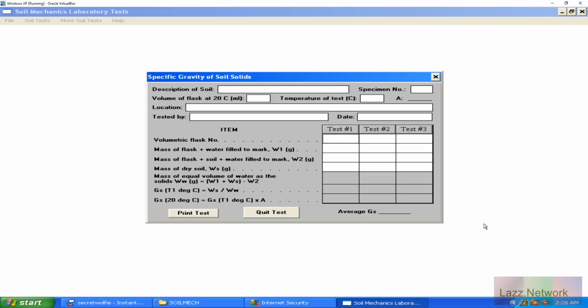Because I've had it happen before where I kind of forgot, or I assumed, looking at the material, seeing that it was relatively sandy, but it was black and/or dark gray, at least with the color, which could indicate that it's organic. Or it may not have a presence of organic smell, where it smells like rotting tree roots, or usually organics don't smell great.